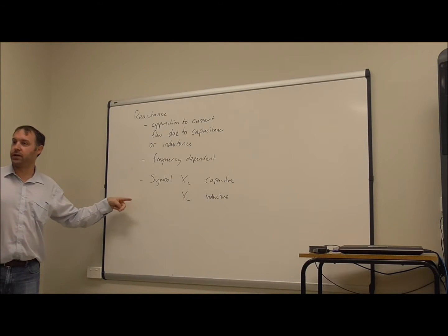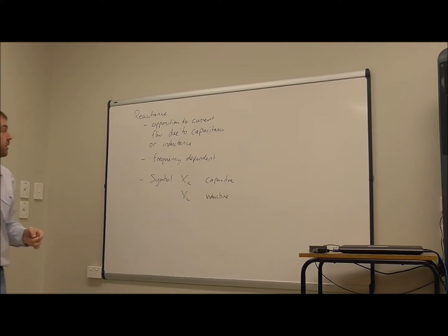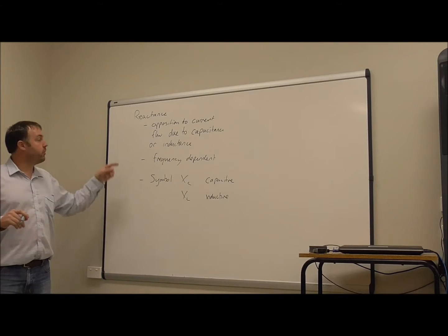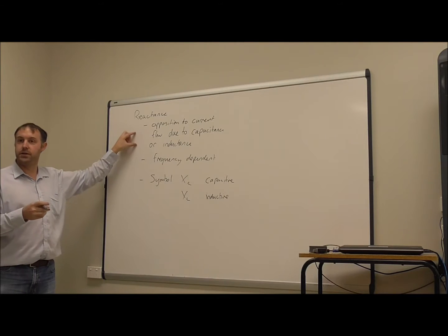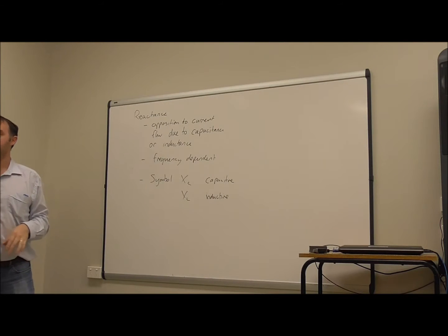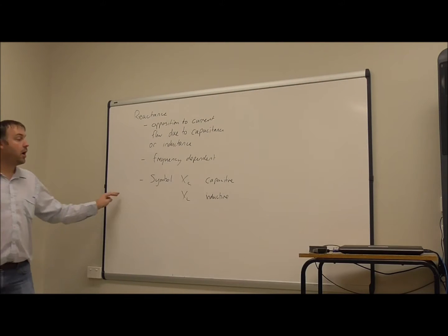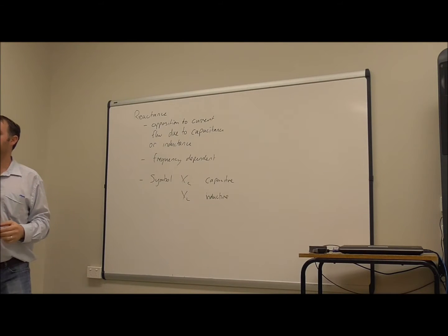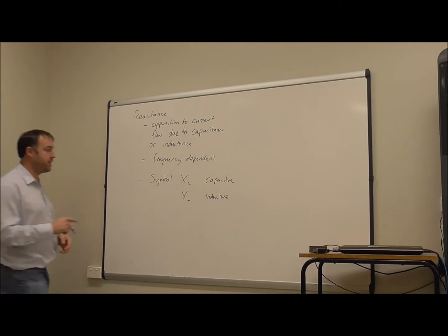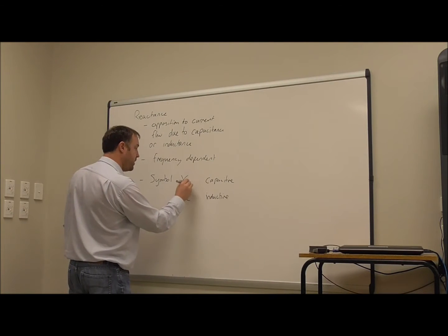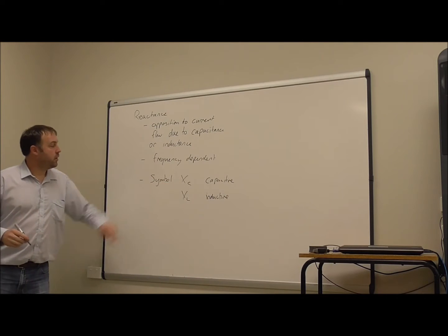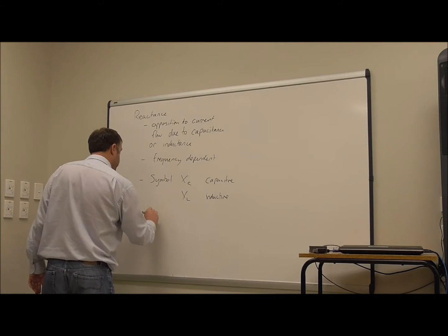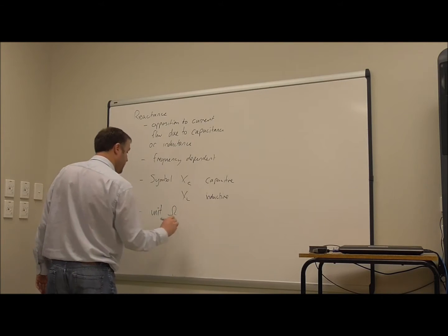Depending on whether it's a capacitor or an inductor depends on how it's going to respond to that frequency. So for a capacitor, the reactance is quite low at very high frequencies and really quite high at low frequencies. For an inductor, it's actually the other way around. An inductor has very low reactance, so low opposition to current flow, at low frequencies, and very high reactance at high frequencies. XC and XL. Okay, so the unit is still in ohms.